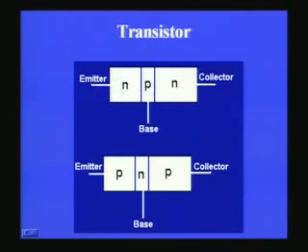One is called the NPN transistor, the other is called the PNP transistor, where the N means it is a semiconducting area which has a majority of electrons, N type charge carriers, namely electrons. So we also know that in this N region there will always be minority carriers, which are basically holes, which exist because of the normal temperature at which we operate.